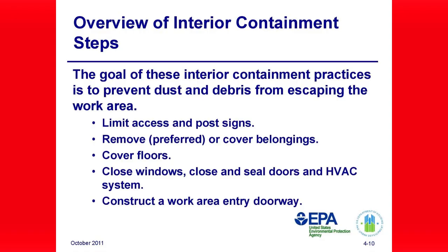Number 6, cover duct openings. All HVACs should be covered, either intakes or regular vents, because you can actually transfer the dust from one room to the other. Remove dust and debris from everything leaving the work area. Use precaution to ensure that all personnel, tools, and other items are free from dust and debris before being removed from the work area.